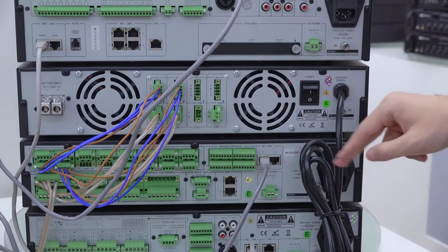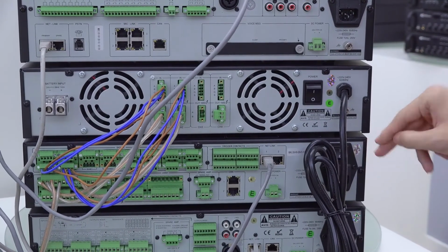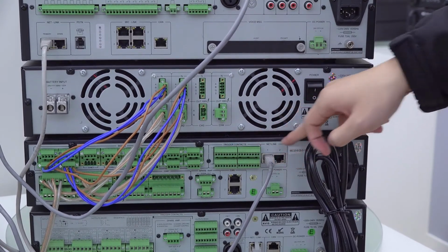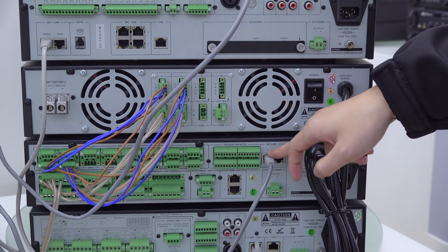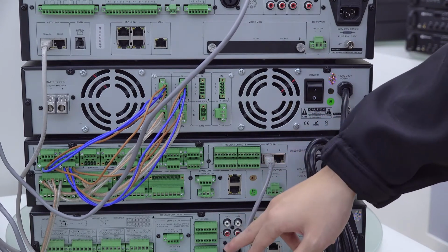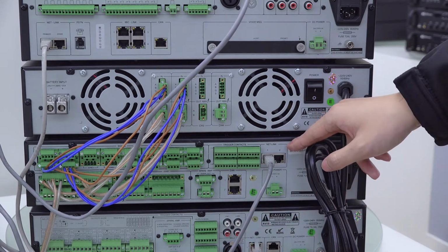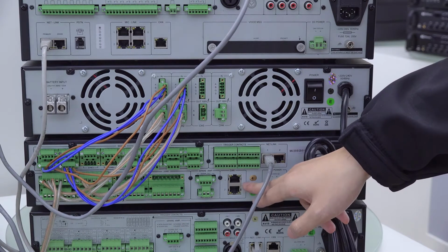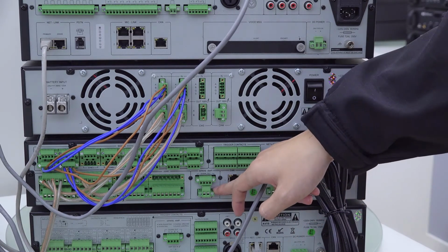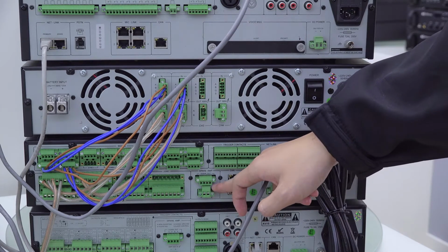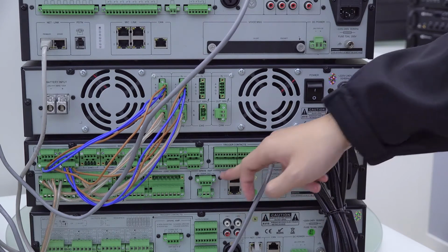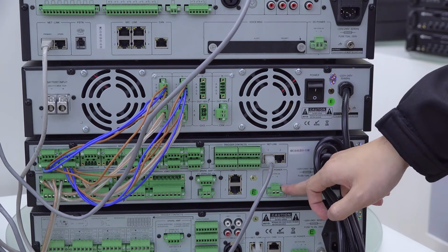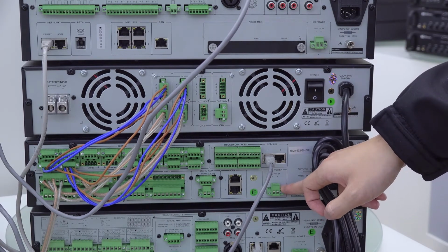Now we come to the changeover rear panel. You can see there are 8-channel dry contact trigger inputs. And this network port is for the communication with the controller. And this is for the CAN protocol communication. It also supports the 1-channel spare amplifier for the backup function. And it also supports the 24 volt battery for the DC supply.